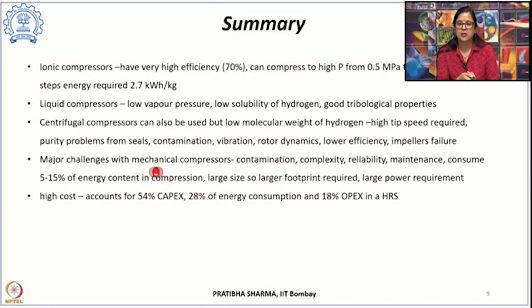At the same time, these mechanical compressors are larger in size. So, the size requirement is big, the required footprint area is also large, and they require a lot of power for driving the compression process. So, there is a large power requirement associated with mechanical compressors, and they have a higher cost.